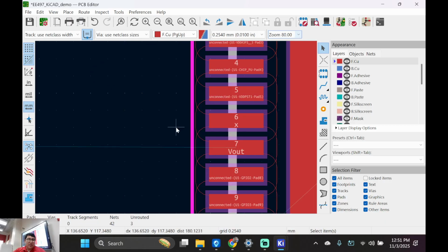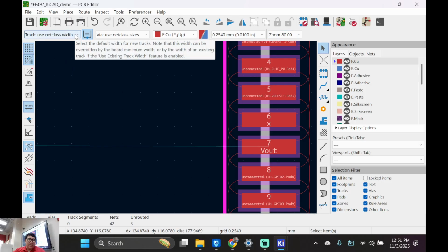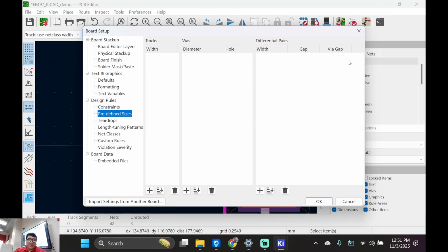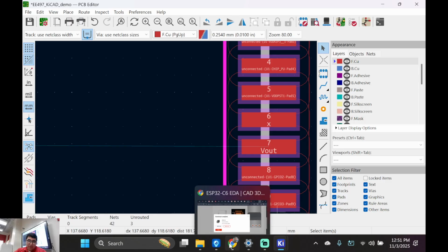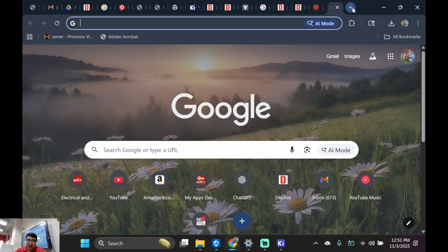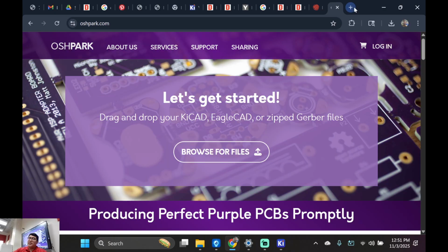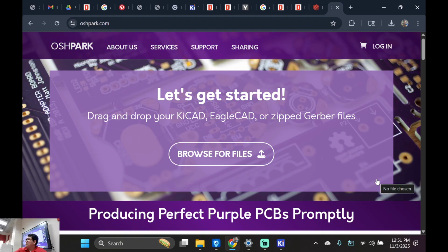So then the next thing I'm gonna do is create a wire. To create wires, okay, it's gonna be under track. Predefined sizes. So here's the tough part of PCB design: you need to know who your manufacturer is going to be, all right? The manufacturer that I use a lot, let me show you, is OSH Park, okay? This is what I use for all our junior design classes, EE320, to get the design board made with this manufacturer.